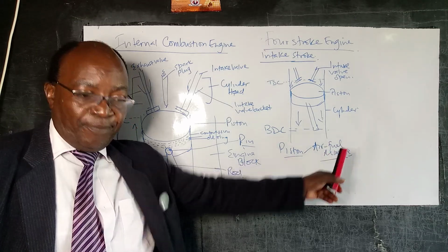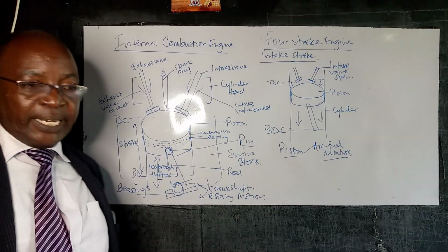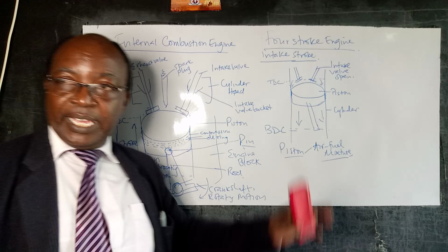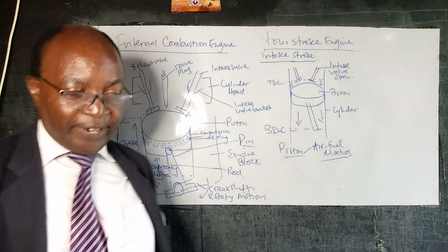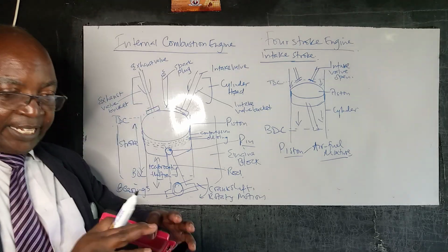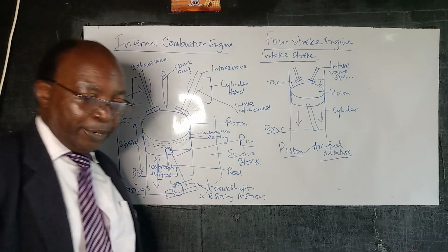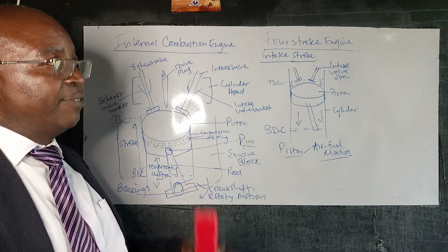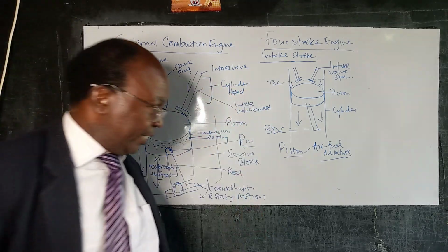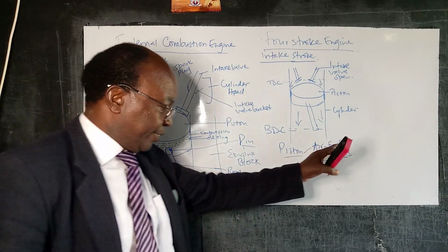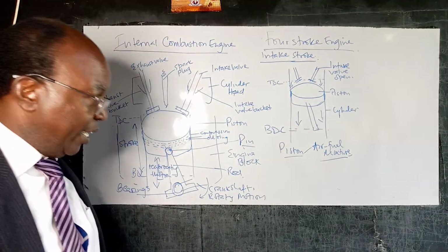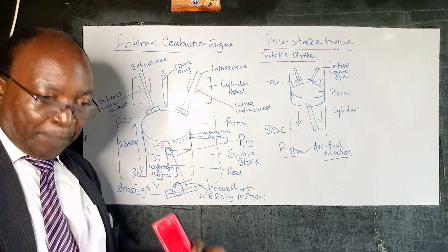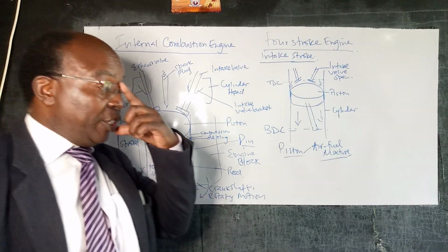This air to fuel ratio is very important in terms of performance of these engines. So that setting for air and fuel ratio is set in the carburation system, which deals with the fuel unit in the engine. That's where the mixtures are configured so that they are in the right ratios, so that you get proper burning and an efficient engine.